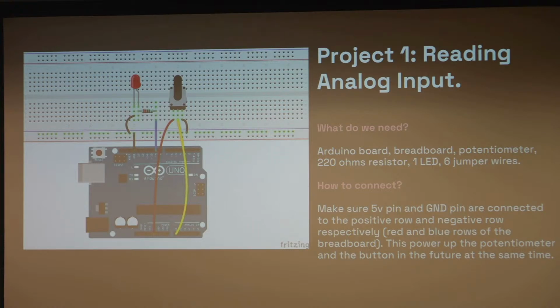Yeah, you need help? Potentiometer, so it might not fit as it comes, by default. You might shrink the legs a little bit, or move it so it fits on one side of the breadboard. Okay, and it's supposed to be how it's here, right? Exactly like that.